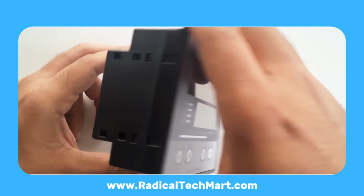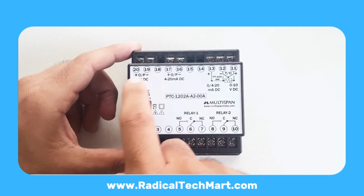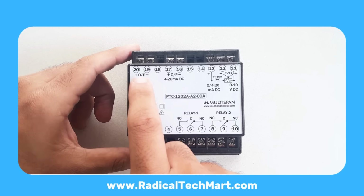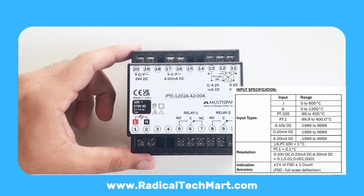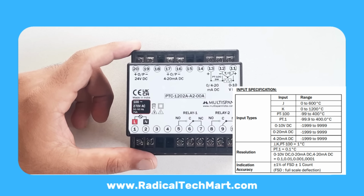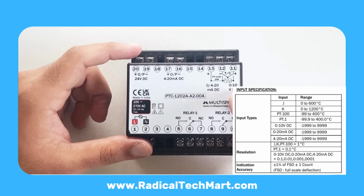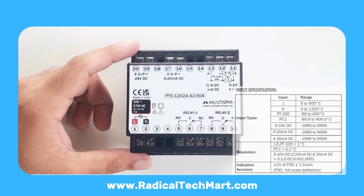24-volt DC transmitter supply on terminals 19 to 20, a constant, built-in 24V DC, 30 mA, to power a pressure, level, or flow transmitter. The transmitter's output then returns to the controller as the measurement input. For inputs, PTC-1202A supports thermocouples J, K, R, E, etc.; RTD, PT100, 3-wire; analog, 0 to 10 volts DC, 0 to 20 mA, 4 to 20 mA. This means you can connect a temperature sensor today and tomorrow switch to a pressure transmitter. Same controller, different input.